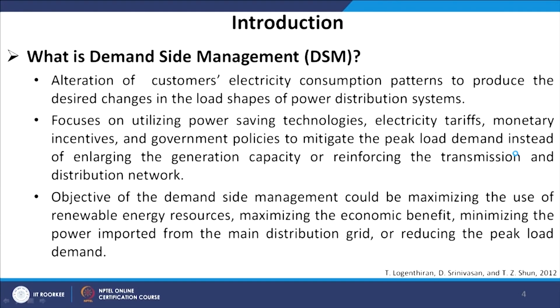I would like to emphasize one thing here: through the smart grid programs we can certainly control the generations as well as the loads. In my previous lecture you might have seen, out of 3 loads connected to a DC grid, 2 of them are non-critical and 1 of them is critical. So, if the load is more and the generation is less, then we curtail some of the non-critical loads from the system so that the system generation and load can be balanced or matched.